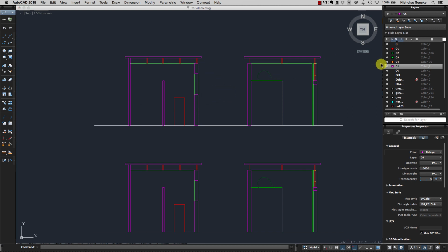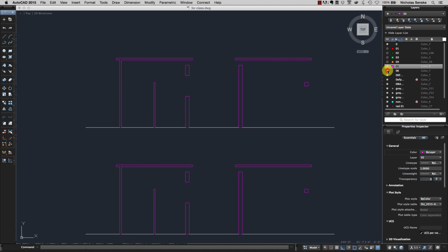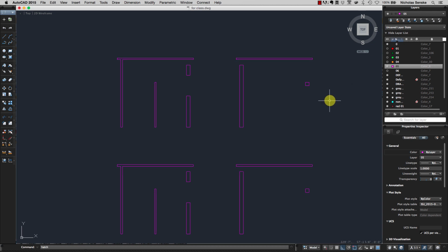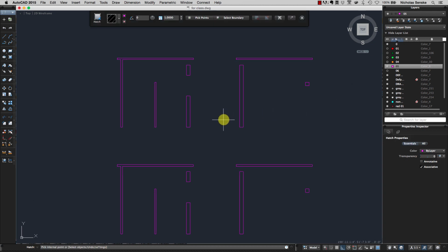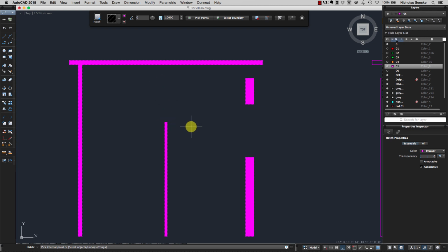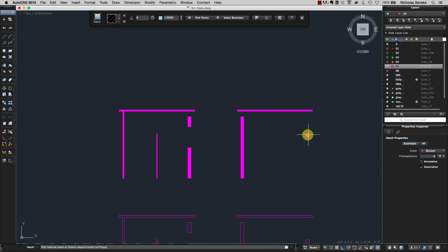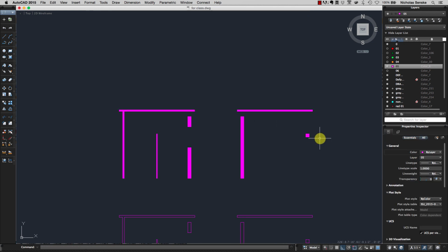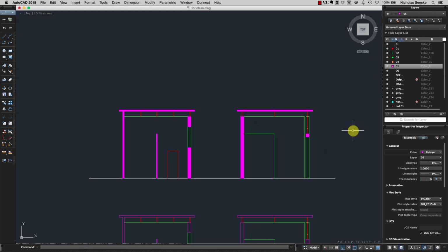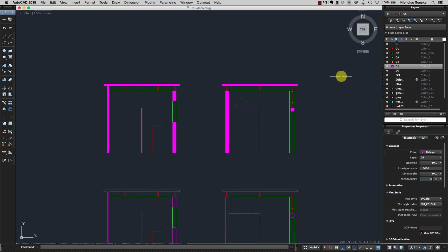If you've done your job and everything is clearly modeled, everything's kind of closed, doing poche with a hatch is pretty easy in AutoCAD. I'm going to go ahead and hide layers here. Maybe go ahead and hide the ground too. Okay, so you can do the hatch command, and it says pick an internal point or select objects. AutoCAD's actually pretty good anymore. You can just click carefully inside of an object, and it will fill that object. And then you press escape when you're done. Easy peasy.